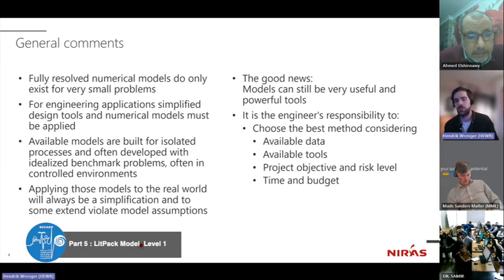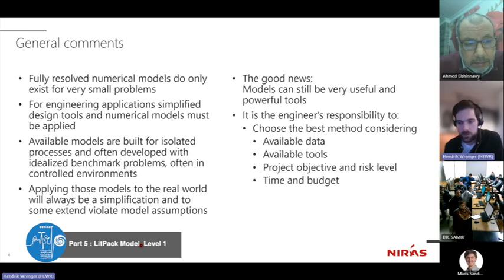So that means, okay, it's okay. You go through a first modeling iteration, just knowing that probably the mistakes you're making are quite large, so your confidence in that is quite low. But for a preliminary design, that can still be sufficient to make some strategic decisions, maybe to initiate modeling campaigns, to initiate sediment sampling on the beaches, identify the profiles you want to model, etc. And then you go back for a detailed design and you do a more detailed campaign with a larger time and budget, for example.